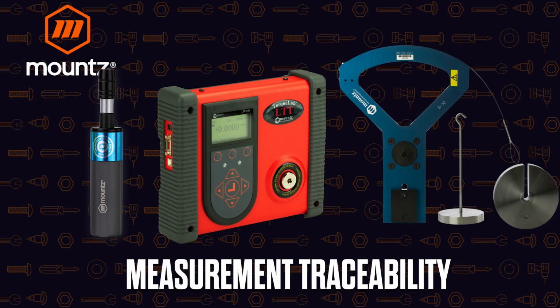If you look at a calibration certificate, the calibration certificate will list whichever analyzer it was calibrated on. That analyzer, if we look at the calibration cert for it, is going to tell us what the dead weights were, and so on. So we have all of that traceability. We can be assured that the screwdriver can be traced back to the dead weights that were used to calibrate the torque sensor.